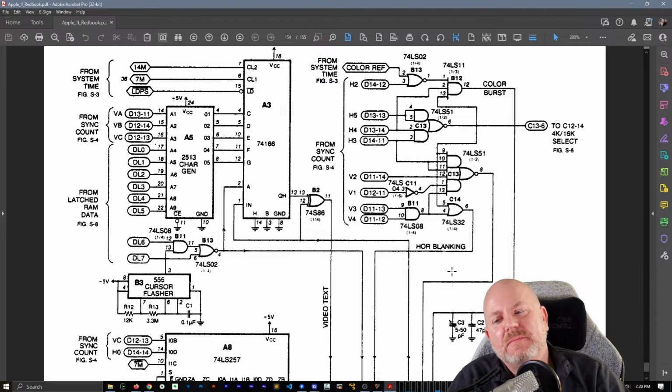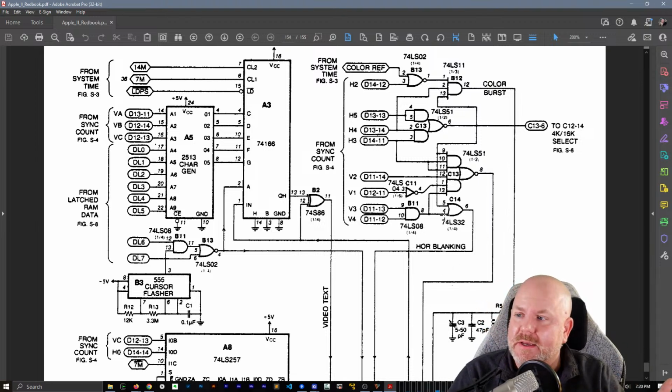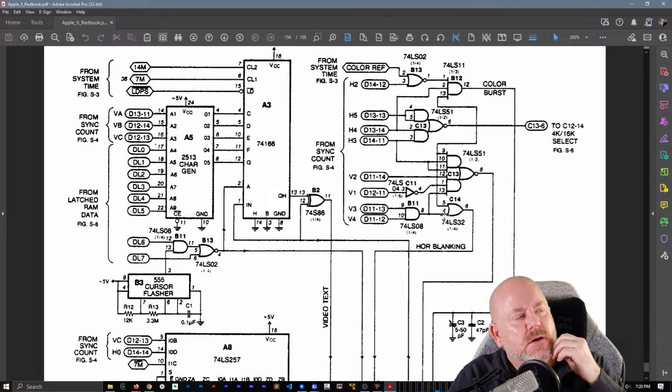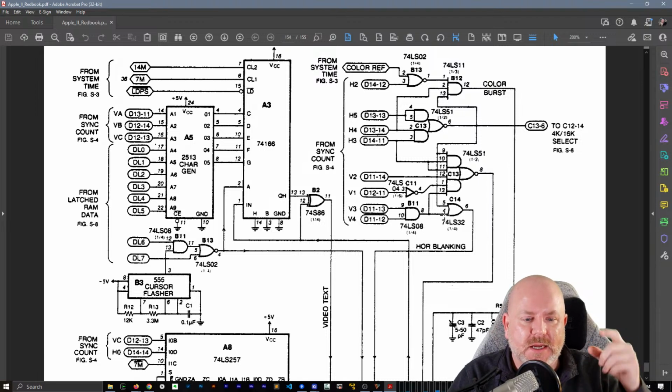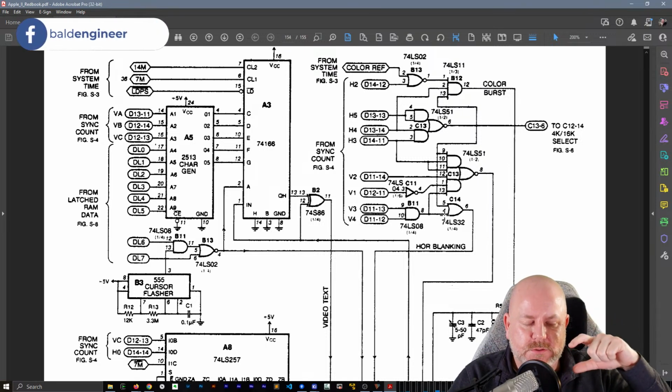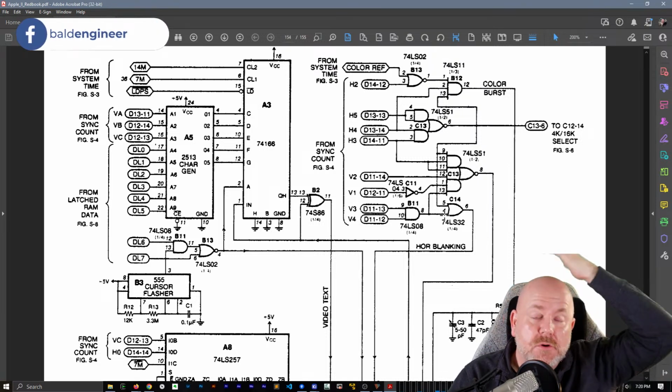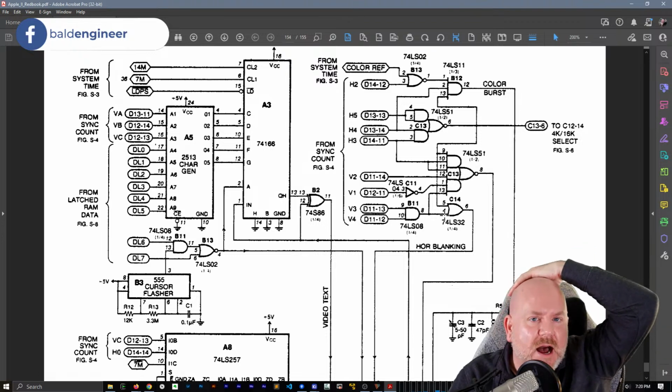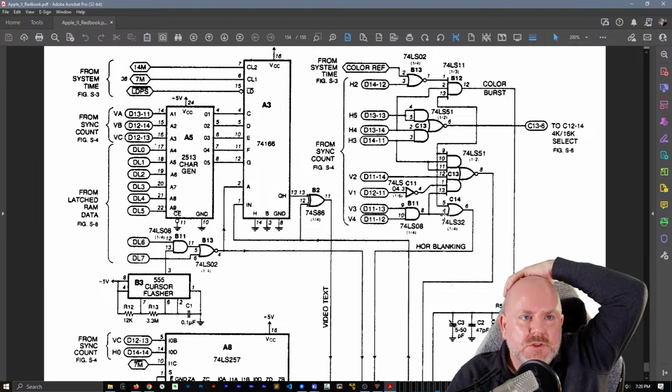Yeah, but the other thing is, if you had some through hole parts, for example, I'm really a big fan of putting the low speed decoupling capacitors on the back of a board.